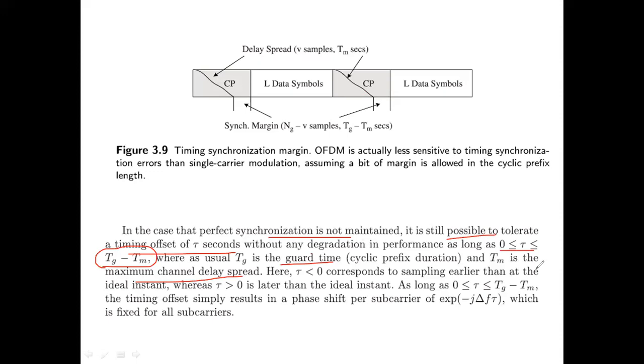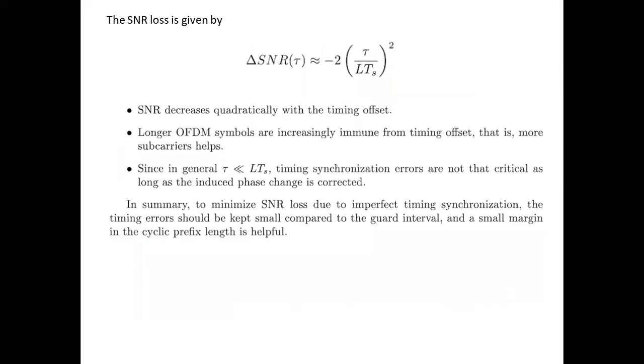While deciding the number of subcarriers to be used, you usually take your bit duration to be 10 times the time delay spread to take care of this. That is the way to counter this: the guard bits and the large value of subcarriers that you have taken. So these things can be tolerated, and timing synchronization is not an issue.